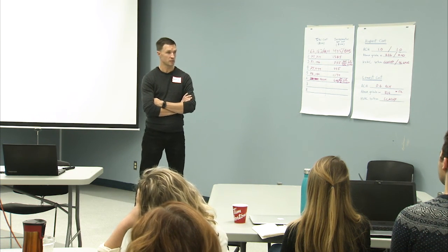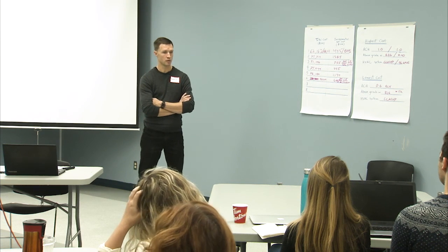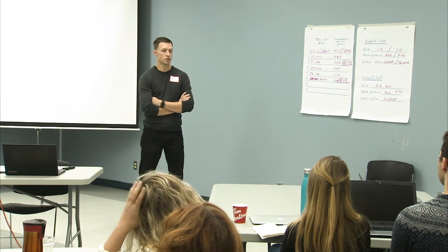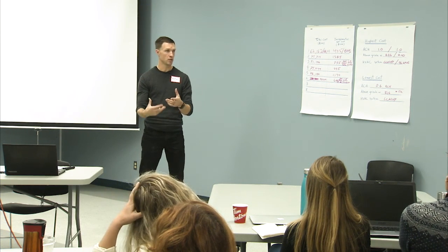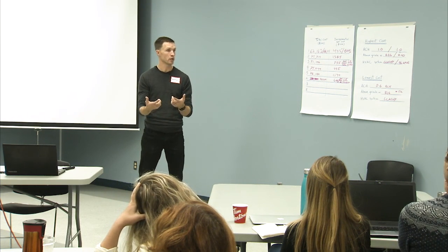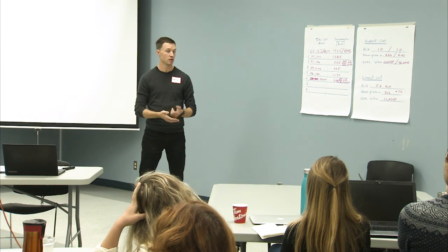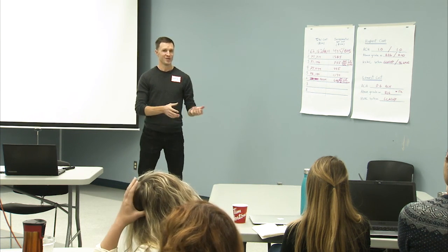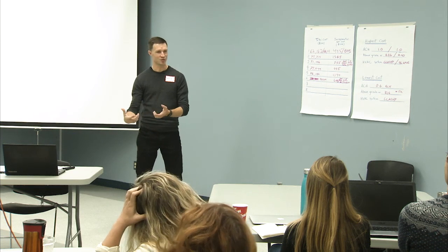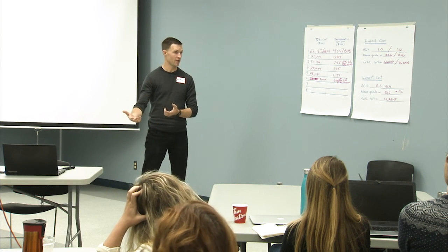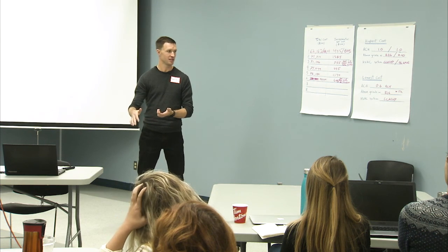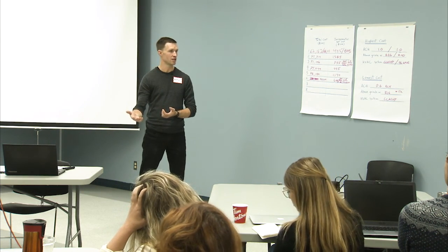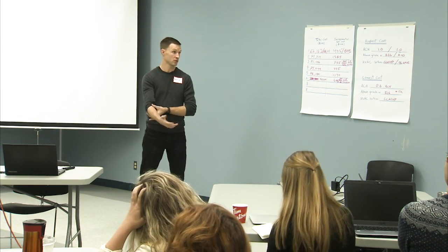I don't think we've experimented with that yet. I think the process that I've envisioned is that you come up with a spec, your energy advisor builds that into your model to see how close you are. Hopefully you're in the ballpark and that you're talking about incremental change. But as you point out, if you put this into the HOT2000 model for your actual design at 1 air change per hour, and then you realize, no, I need to be at 0.6 to actually get to net zero, have you suddenly adopted a whole bunch more costs that change this whole equation? It's a good question as well.